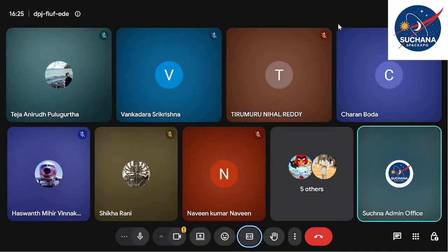These are drilled on a PCB. And coming to the plated via or PTH, they have copper barrel conductors. Plated vias have a copper barrel conductor. That means it is just a hole, but it has a copper layer throughout its circle. And then the second one is the non-plated via or NPTH, non-plated through hole. They do not have any kind of copper layer.